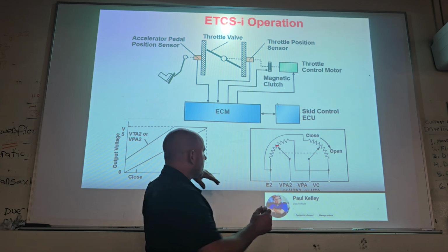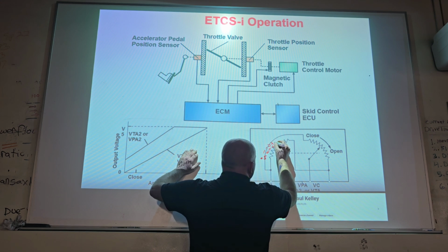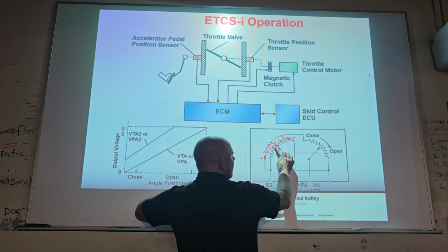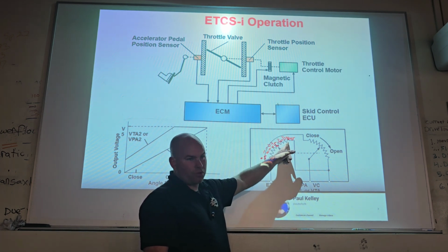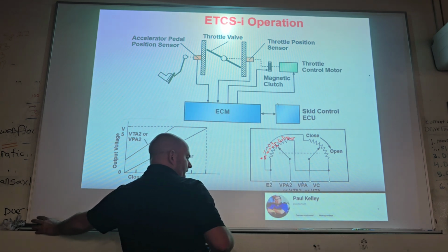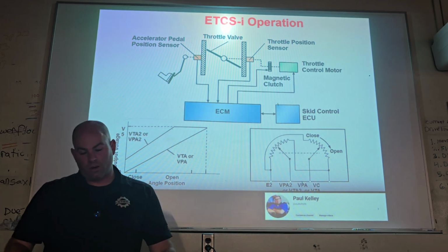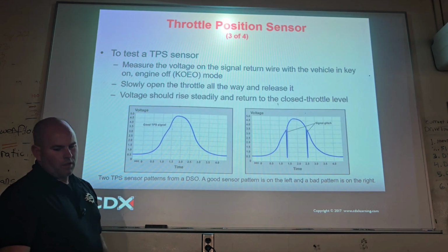Remember that? So let's just say this is 0.5, 1, 1.5, 2, 2.5. Let's say this one's at 2.5, 3, 3.5, 4, 4.5. If every time you get to 2.5 volts, it drops to 0, it's literally this resistor grid in here. See what I'm saying now? That type of question has been on the ASE periodically. That could also be on A8, by the way, and even L1, but L1 usually gives you something harder than that.